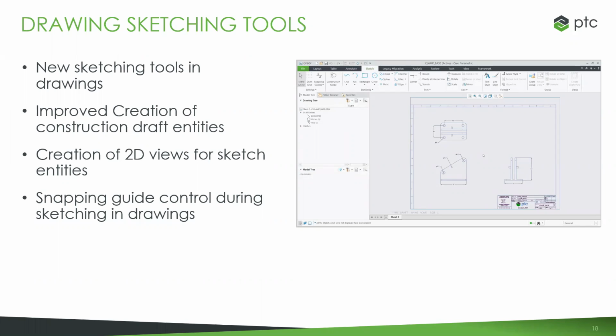And that's starting with the ability to create drawing views. So this allows you now to import a 2D drawing. You can select all the entities for a particular view and now identify that as a drawing view. So you can do that for each of the drawing views that you're importing. And then from that point, you have the ability to define the relationships and the dependencies between those drawing views. So you could say now, this is my front view, the top view is a projection of my front view, things like that. And this then builds those interdependencies between the different views, meaning that if I scale one of them, the other views will update accordingly.